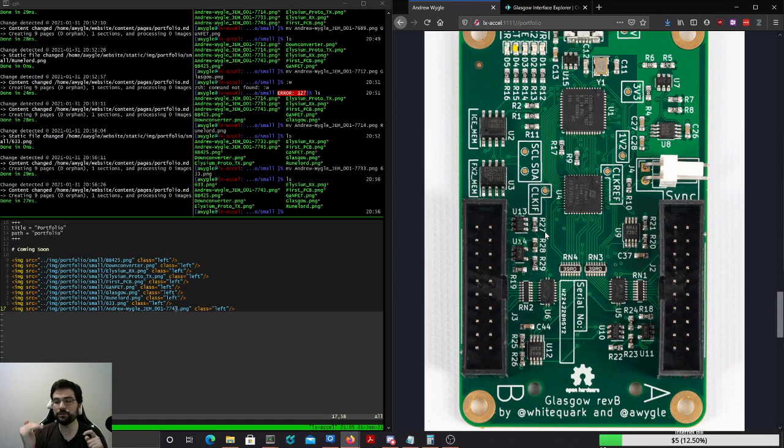you can tune the boiling point of this liquid. It's inert. It doesn't affect you or hurt anybody. You can change it so that it boils at the solder's melting point, or whatever temperature you want to bring the board up to. Then you heat the liquid. It boils. The vapor comes up, but then it hits the board, which is cold, and it condenses.